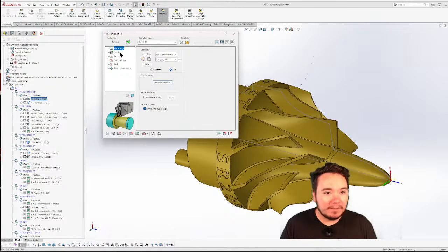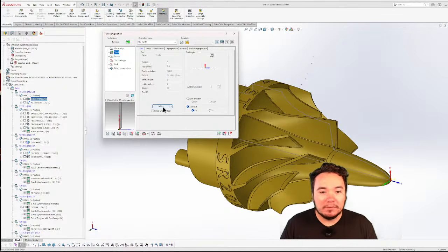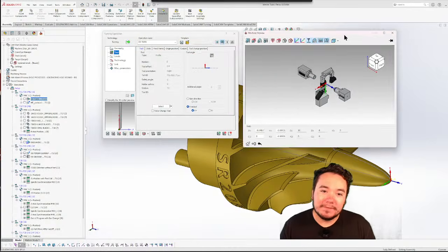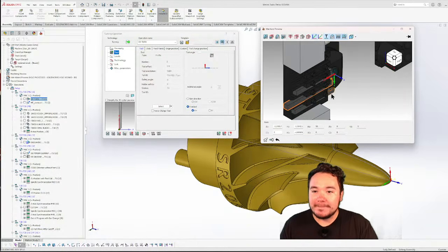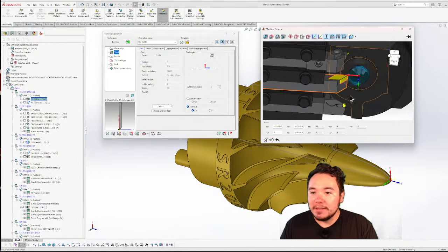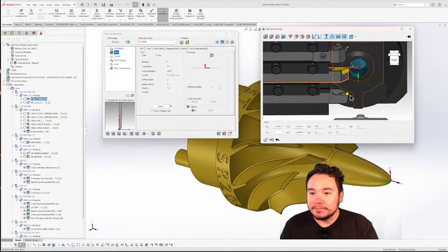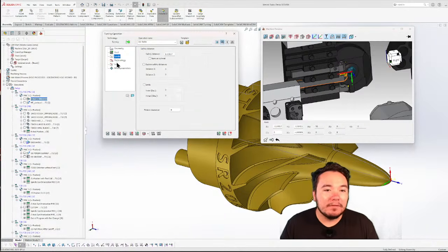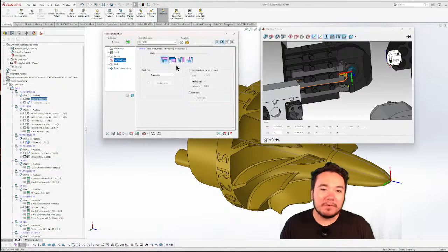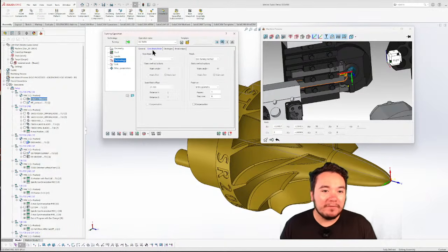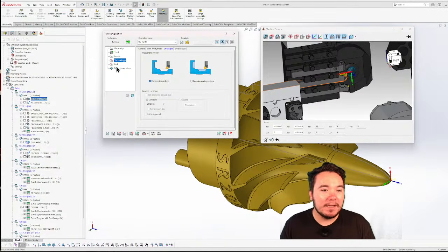That's pretty much that. Selected my tool, and you can see the tool here in the machine. Got everything modeled in. Awesome. And then from there I can select if I'm going to do a finish only, or if I'm going to do a rough. So this is straight to finish. Since we're working on a Swiss machine, it's got that rigidity because that guide bushing is there. ISO turning method, entire geometry. I did not break any of the edges or anything like that.